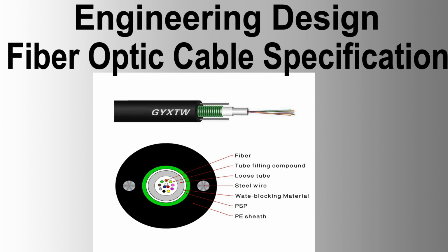Buoyancy control. Buoyancy control measures, e.g., sandbags, set-on weights, shall be considered to ensure negative buoyancy is maintained for the conduits without fiber optic cables installed. Buoyancy control methods of installation shall be subject to company approval.